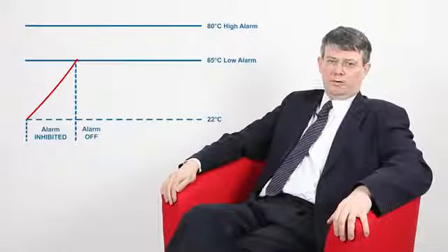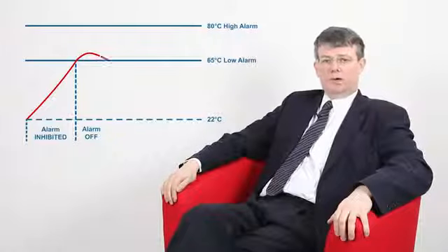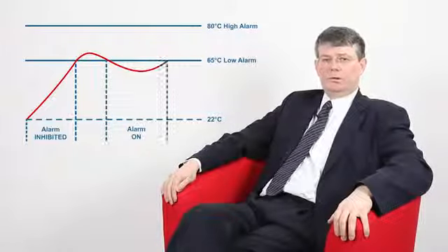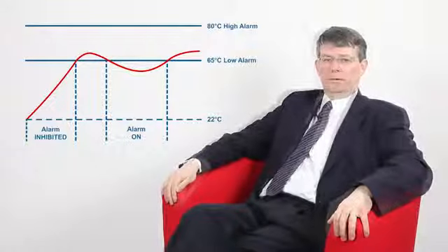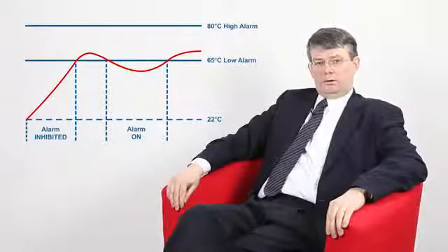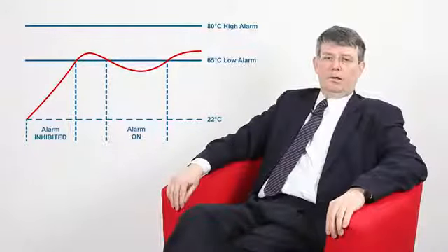With the Inhibit function active, the alarm will not actually activate until the process has first got into a condition where it would not be active and then move back into the active condition again. Only from that point onwards does the alarm activate and work normally. The high alarm that you set at 80 degrees C would already be in the non-alarm state as you powered up, so wouldn't be inhibited, but then of course it wouldn't be active either, so that's not a problem.